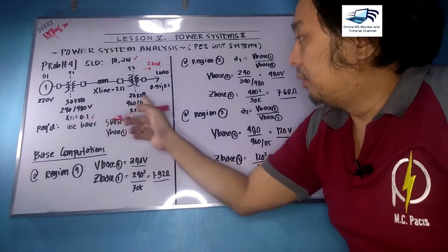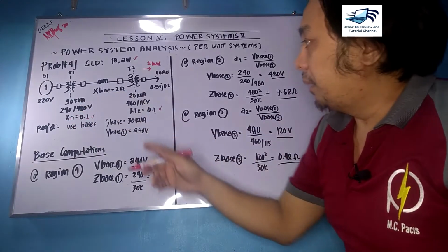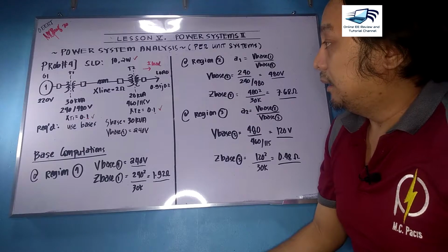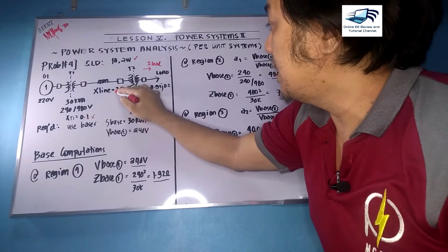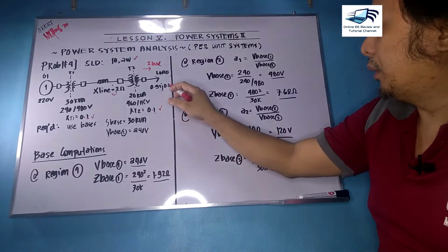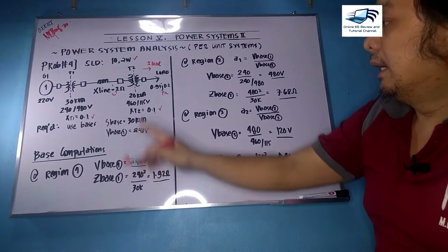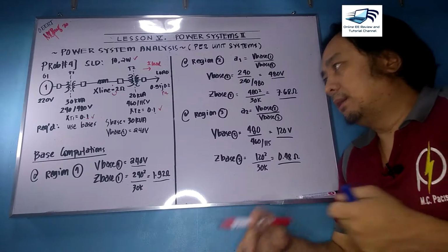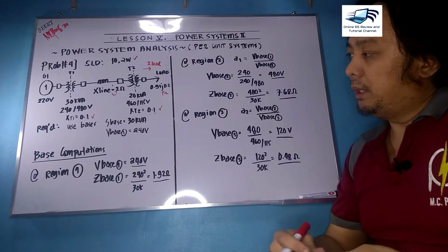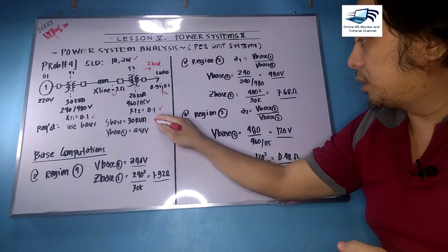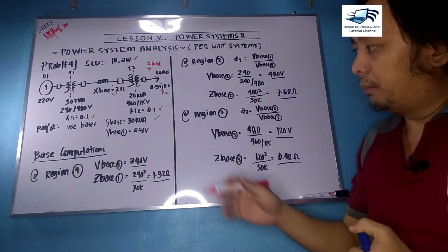And then you have your voltage, your apparent powers, your line impedance here. So this X line, you expect there is a J there. And then you have 0.9 plus j0.2 per unit as well for the load, and you have a 220 volt. Okay, now on the problem, we must use the basis of S base, which is 30 kVA on transformer 1.